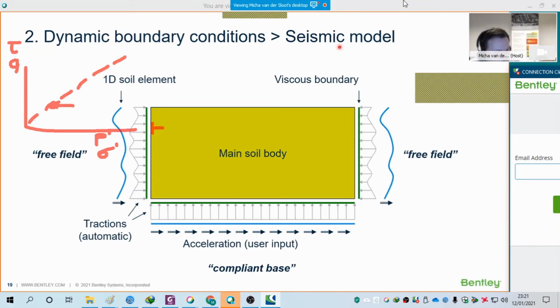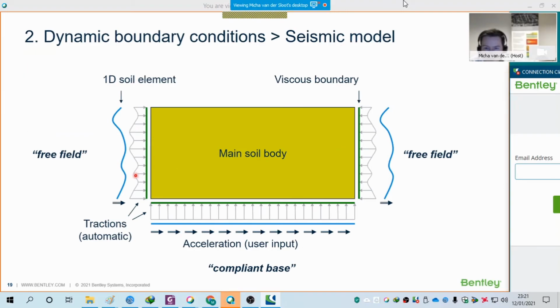If we consider the same boundary conditions for a variety of soil medium, yes, you can just use the same boundary conditions if you have different soil medium. So if you have clay and silt, all boundary conditions can handle the same. You do not have to apply something different, because the dampers that are part of the system also take into account adjacent soil material. The free-field elements here also take into account the adjacent soil, so it will take the same properties. So that's perfectly fine.